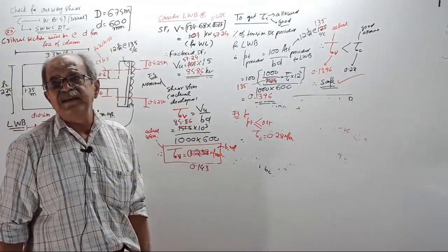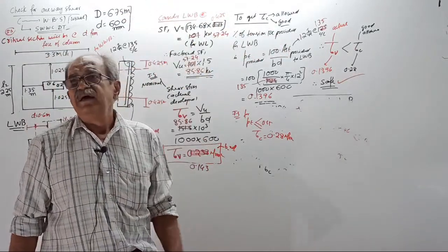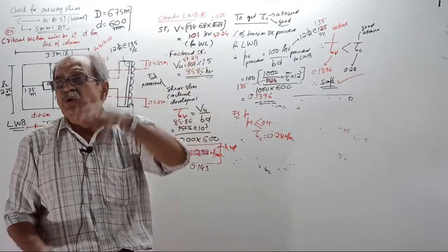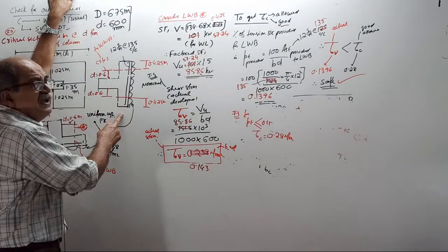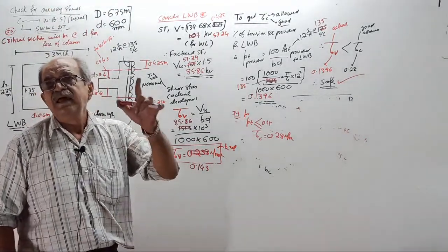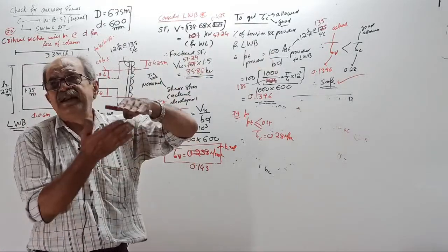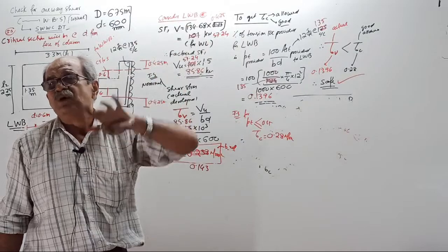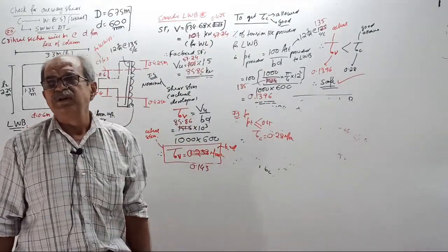When you increase the depth, punching shear check is not required once again. And the required steel will reduce. Some people will maintain the same steel. Okay, that is there. But one thing, if minimum steel is given, you have to give more. Why? When you increase the depth, minimum steel will become more. You should be careful about that. Or you calculate the steel once again.